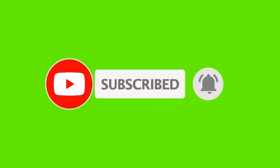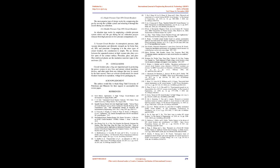There are two types of SF6 circuit breakers. 4.1. Single pressure type SF6 circuit breakers. The most popular type of design works by compressing the gas by moving the cylinder system and releasing it through the nozzle during arc extinction. 4.2. Double pressure type SF6 circuit breakers. An obsolete type that works by employing a double pressure system, in which the gas during the arc extinction process is released from a high pressure to a low pressure compartment.